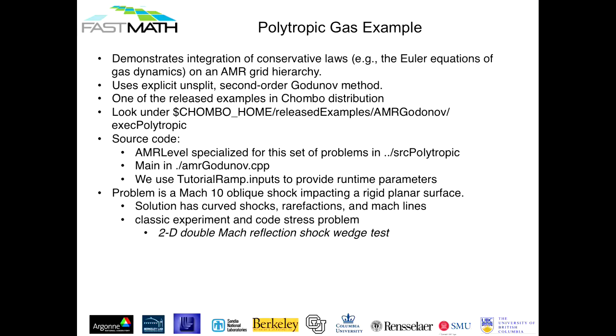It's under AMR Godunov. Godunov has several examples where we use second-order Godunov shock capturing techniques. So this is shock capturing, not shock tracking. Shock tracking is a different technology. We also do shock tracking, but you need more machinery to do tracking. In shock capturing, you try to make sure your shock stays within 2 cells. So you get a sharper and sharper shock as AMR can really zoom in on that shock, and you can control your error very well.